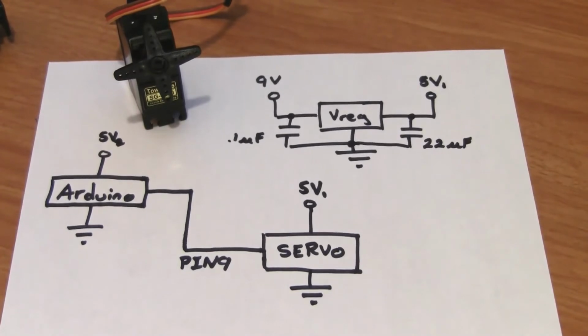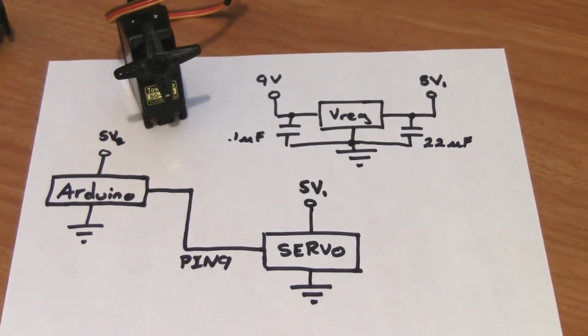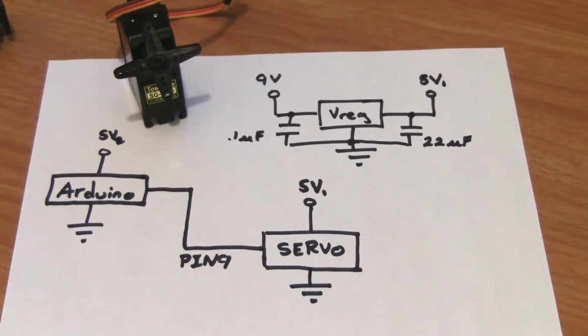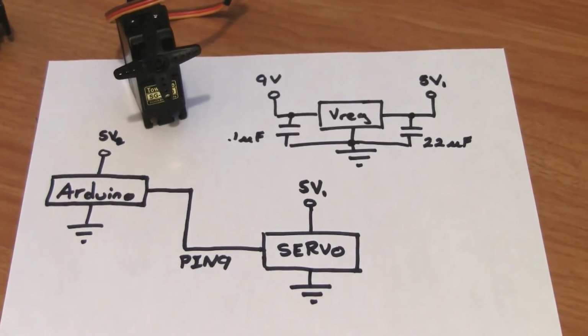Servo motors are much different from DC motors. Instead of just giving them a constant voltage and watching them rotate forever, servo motors respond to a PWM signal. Depending on the value of the PWM signal, the servo will rotate to a particular location. In the case of this servo and many hobbyist servos, this one is limited to 0 to 180 degrees. Based on the value you send it, it will rotate to an exact predetermined position. This is really useful for a lot of projects.